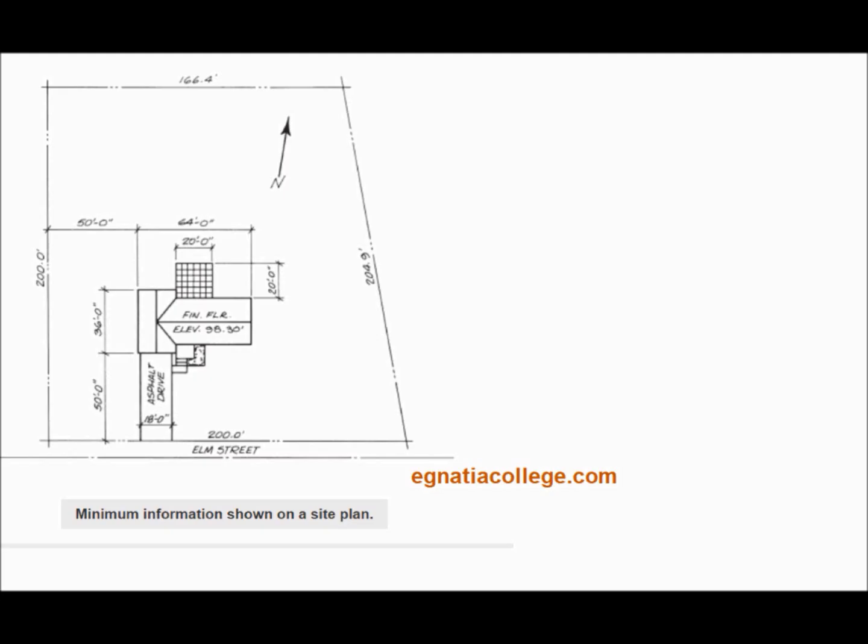Surveyors and engineers usually work with decimal parts of feet, rather than feet and inches. A symbol or north arrow of some type indicates what compass direction the site faces. Unless this north arrow includes a correction for the difference between true north and magnetic north, it may be only an approximation. However, it is sufficient to show the general direction the site faces.